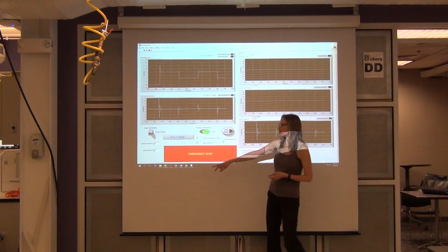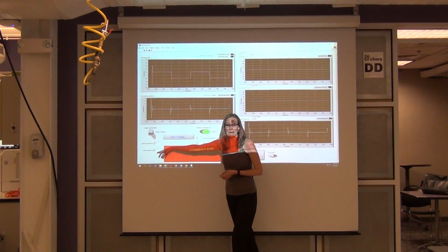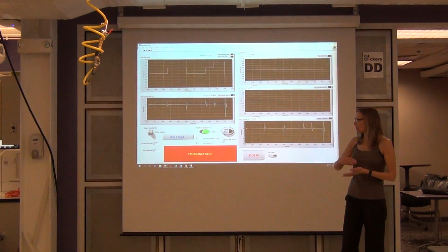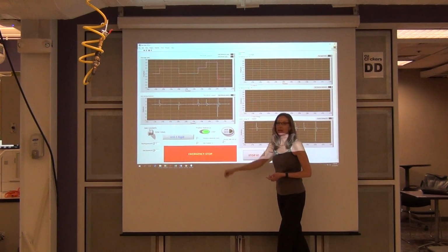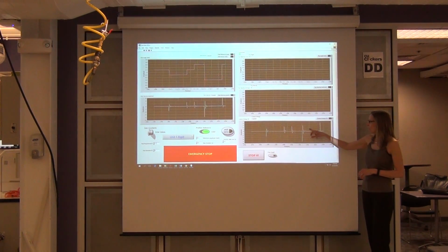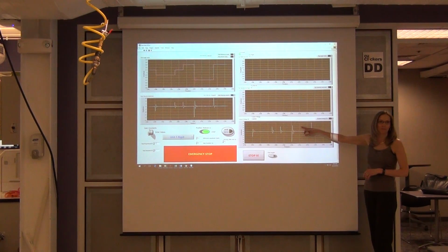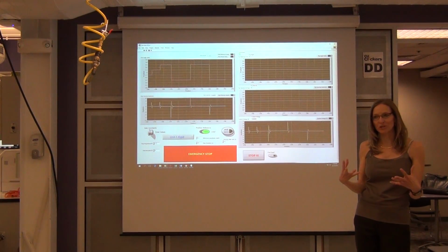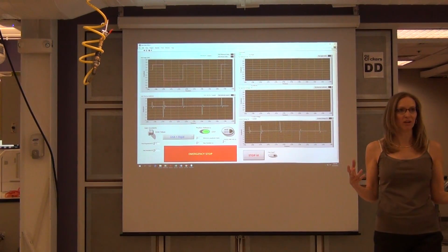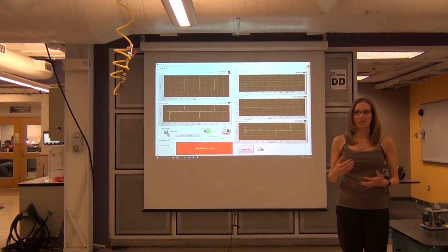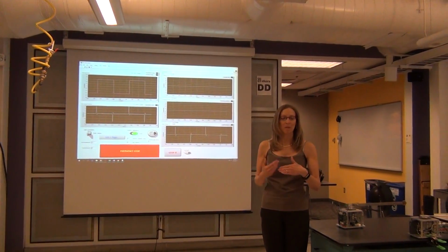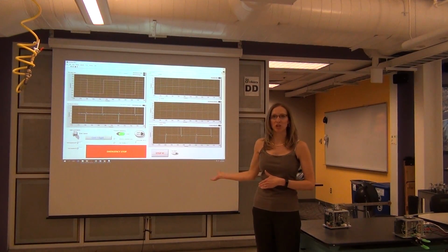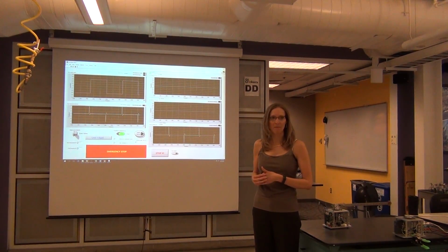Or you can adjust your gains and bring your gains down, especially your proportional gain, which is telling it to go too fast. You can reduce that down, and now you can get back to that 0.3 radians without exceeding 5 volts. So those are your design constraints. This is a design problem for an engineer, very typical in aerospace systems. To design a system, to do performance based on your limitations and how much friction and what the motor voltage can do. Okay? Kind of makes sense?